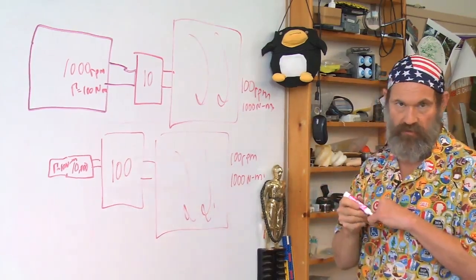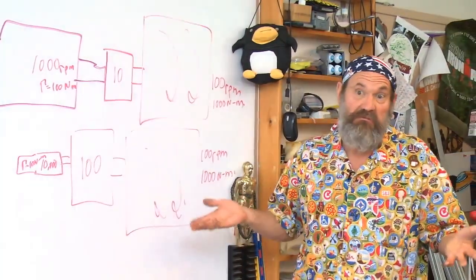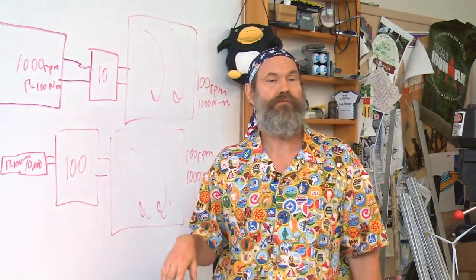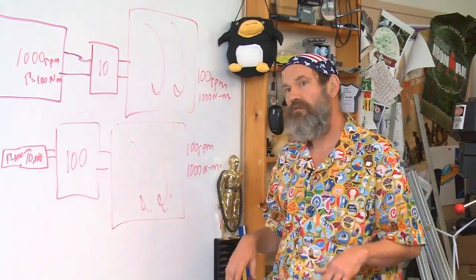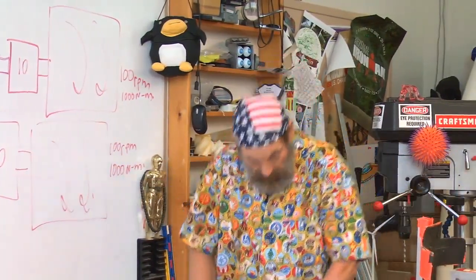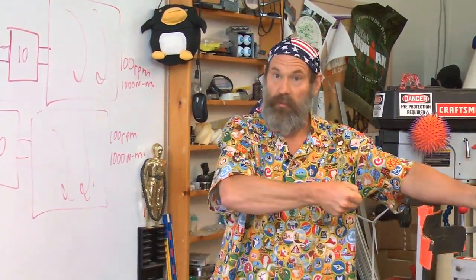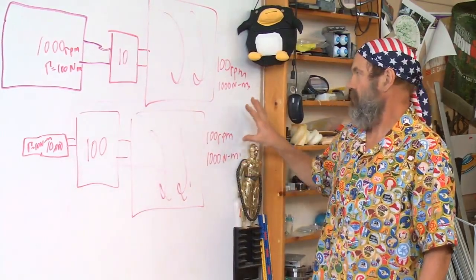And what is the feel of 1,000 Newton meters? Well, my mass is about 75 kilos. Which is around 750 newtons. So if I take on my truck when I get a flat, I put the breaker bar, the socket, the breaker bar, and a long pipe out about that long, and I stand on the end, that'll generate about 1,000 Newton meters of torque. So me standing on the end of a lever arm about 1.2 meters long gives you that 1,000 Newton meters of torque. So this is a pretty severe load.